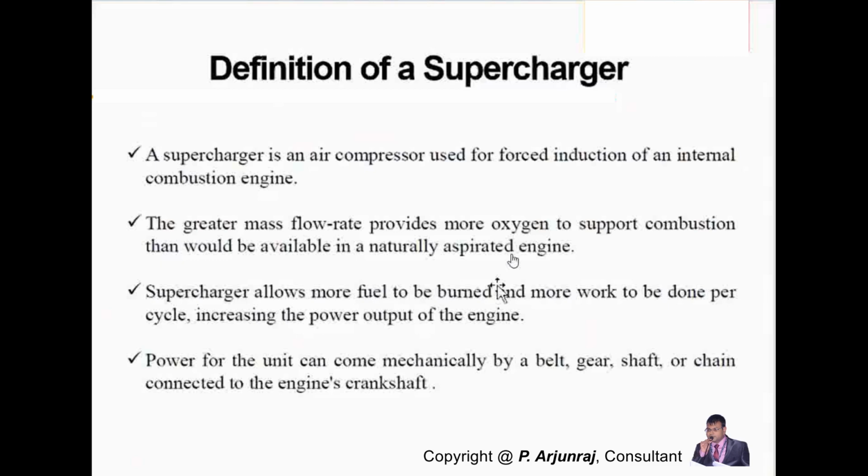Okay, so I told you the volumetric efficiency depends on the ratio between the mass flow rate of the air which is inducted to that of the theoretical mass flow rate of the air. So when it is the mass flow rate of the air inducted, now I'm speaking of the numerator, it's practical, and when it comes to the denominator it becomes theoretical. Practical is nothing but what happens during the operation of the engine in a practical condition. It can be in a higher altitude condition or in a lower altitude condition, irrespective of the condition, how much is the mass flow rate of the air which is induced into the system? That will have the greater impact in determining the volumetric efficiency.